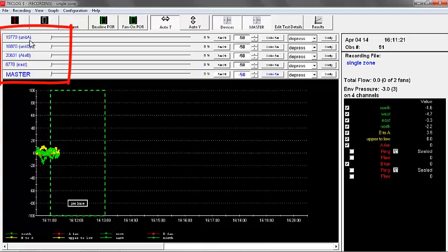And you'll notice each DG700 has a fan slider to control the fan and a cruise pressure that we can enter. So we can use any of those gauges, the fan control tap off of any of those to control up to 6 fans. So each DG700 could potentially control 6 fans if you wanted to set it up that way.